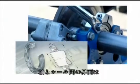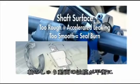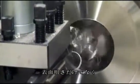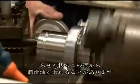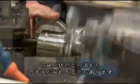The shaft seal interface has a synergistic relationship, relying on the equilibrium of a fine lubricant film between seal and shaft. In addition to the surface roughness, the machining finish on the shaft is a critical factor for reaching equilibrium and achieving good performance. During the machining process, fine grooves are inadvertently machined into the shaft. These grooves, helical in nature, are potential areas of leakage.